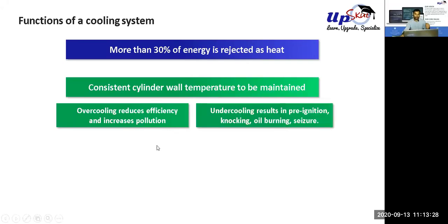And undercooling results in a lot of problems. Most of you know that undercooling will result in pre-ignition or knocking. Sometimes oil will burn if the cooling is not sufficient, and in worst case scenarios the engine might seize.